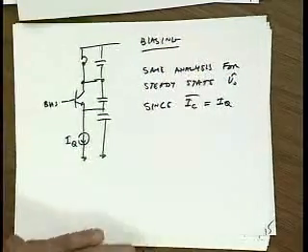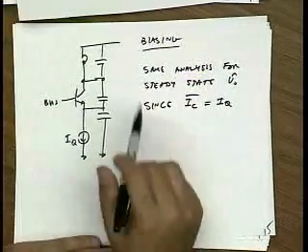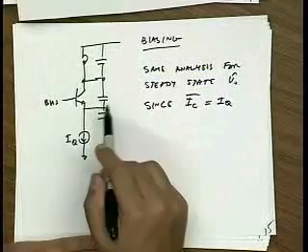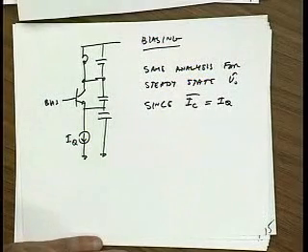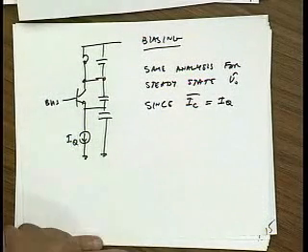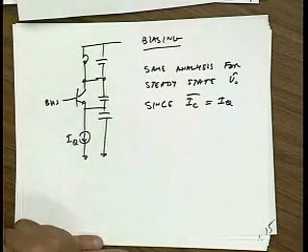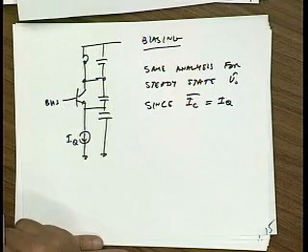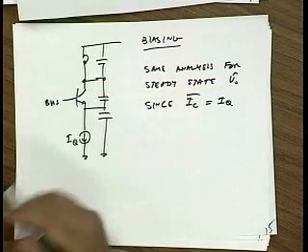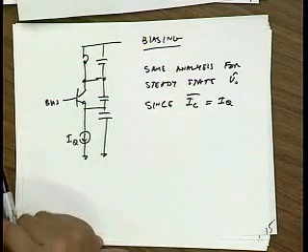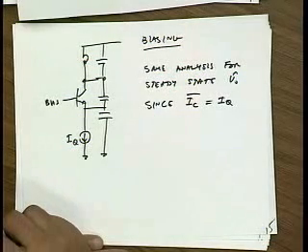Okay? And you can see that this one is a lot more amenable to integration. It almost looks like something you could just pop into an integrated circuit. You got a current source here, got these capacitors. You can build these capacitors very easily in an integrated circuit process. You can use basically just the metal layers that you get for free and build up pretty nice capacitors here.